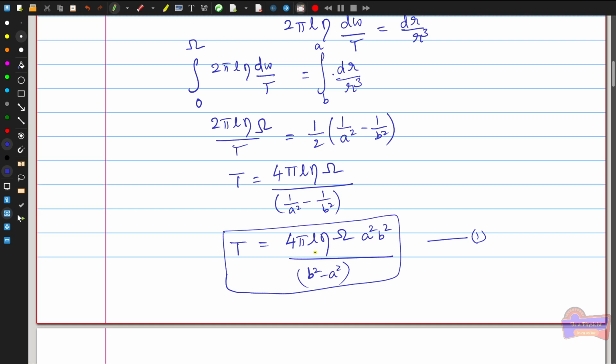So this torque actually tends to accelerate the motion of the fluid in between the layers C and A, but this fluid being in a state of stationary motion, the inner cylinder A must also be exerting an equal retarding torque, that means opposite torque, on the fluid in contact with it. And since action and reaction are equal and opposite in direction, it follows that the equal and opposite torque T is also exerted on the inner cylinder A, tending to rotate it through some angle theta due to this torque motion, until it just balances the restoring torsional torque T.